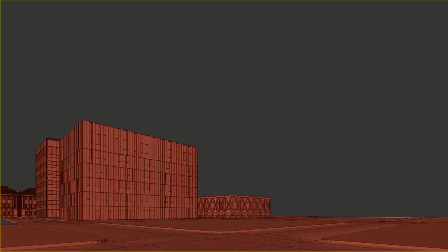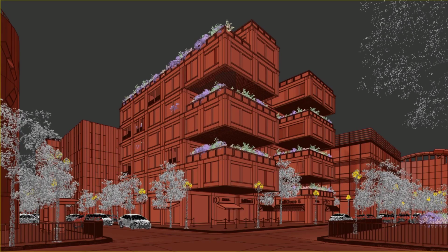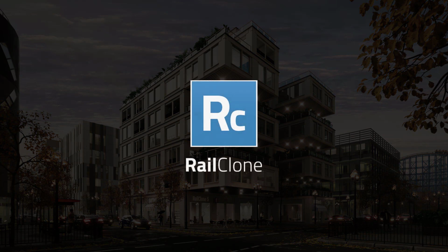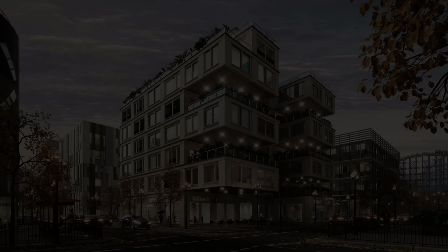Having learned how to use and adapt the library in the previous videos, it's time to start creating your own styles. To do this, it's important to have a good understanding of how base objects, segments, and generators interact. In this video, we'll learn how to use an L1S generator, a linear generator, to create a facade for our central building. Along the way, we'll systematically go through the key settings that determine how a parametric object is constructed.